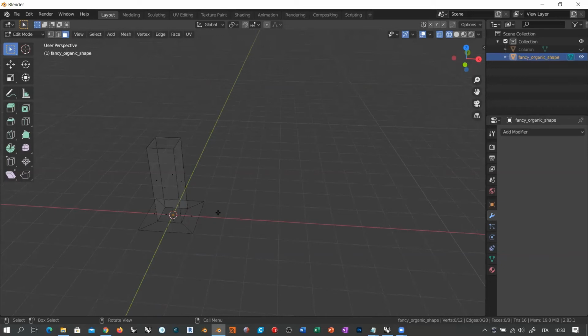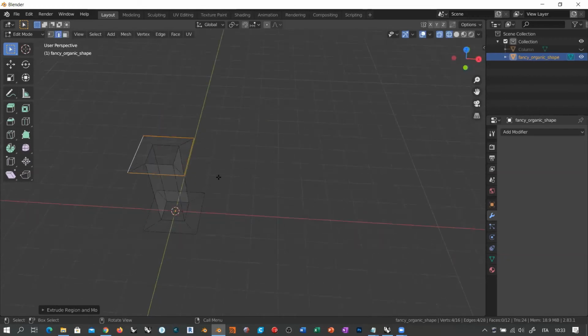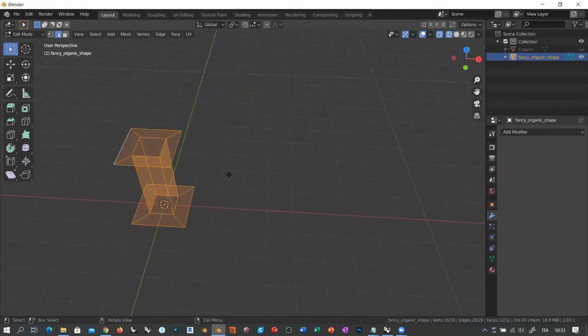and switch to edge selection and select 1, 2, 3, 4 edges, and then extrude them by scaling them with S. E extrude, S scale, so I give them this kind of width on top. So everything is identical to the previous step, right? But now what I want to do, I want to select everything. So the whole set of elements that we have here. And I want to copy this object to the right along the x-axis.